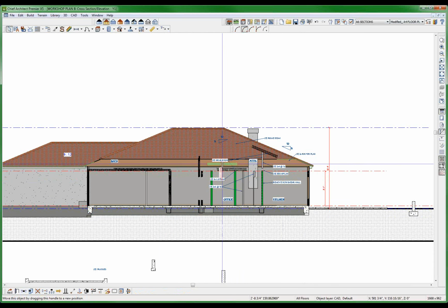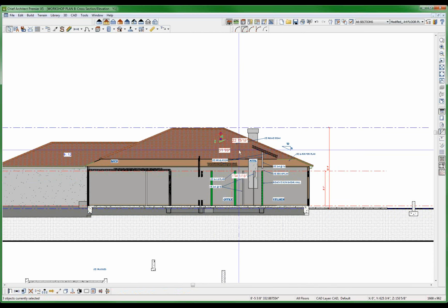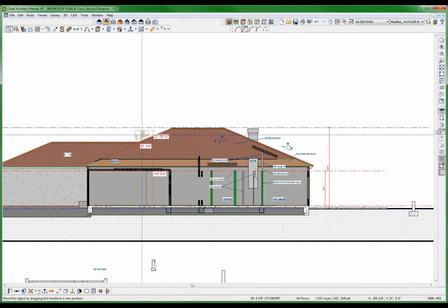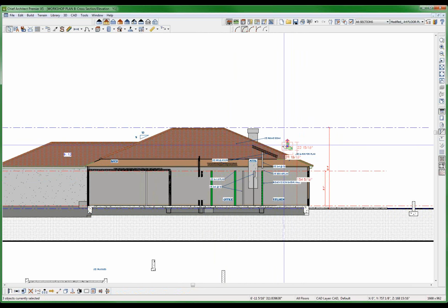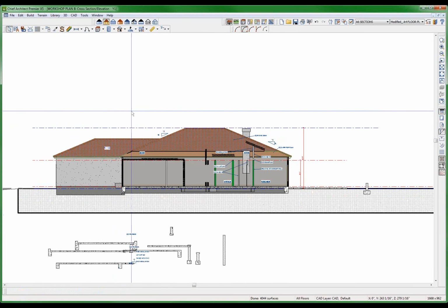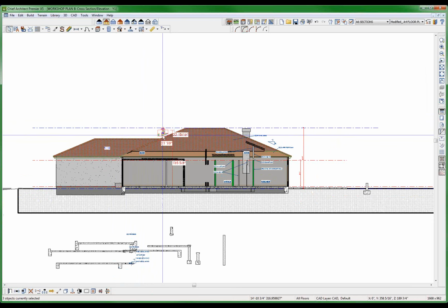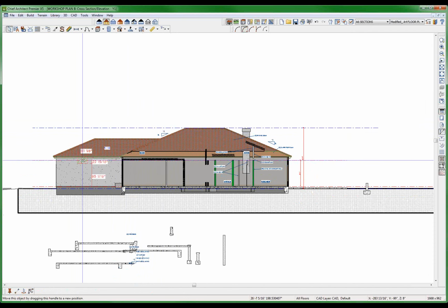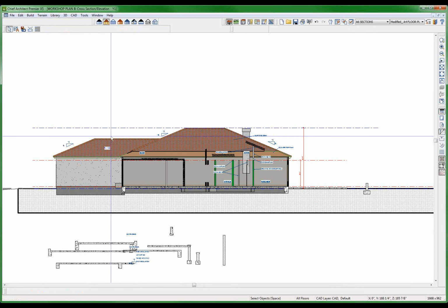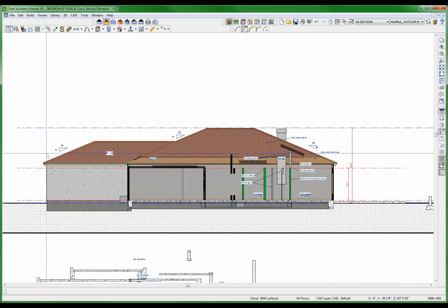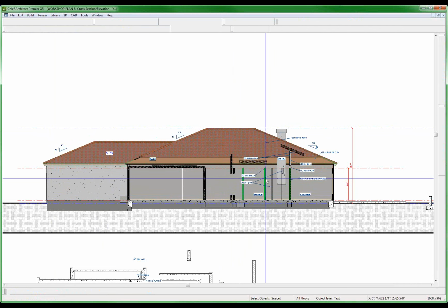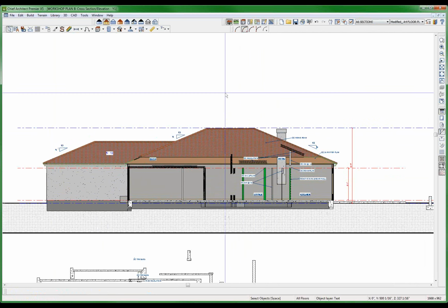The insulation is really right up here. Now I take this pitch right here and stick it there. This pitch is right here. That's fine. And these things should be macros too. This 5 should be a macro. I copy it, and I want to put it right there. And if it's a macro, then all these numbers change. If it's a 4 and 12 or 5 and 12, it's just automatically changed. I don't have to change those numbers. It's just changed in one spot. So you get the idea.